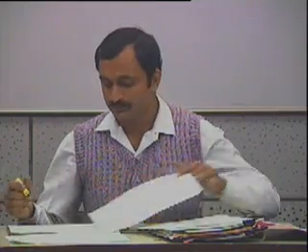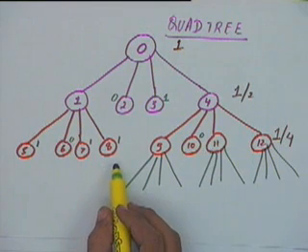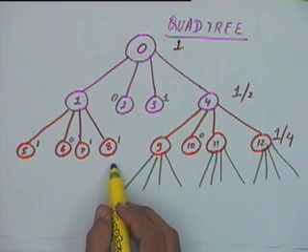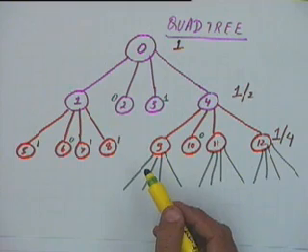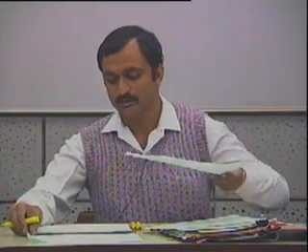If I want to find out the volume, I only have to traverse the tree and I will get the volume. Similarly, if I want to get the moment of inertia, I only have to traverse the tree. For a tree like this, for all the leaf nodes, we will compute the property, either the volume or the moment of inertia, and add it up. So that can be done quite easily. Any question about quad trees and octrees?